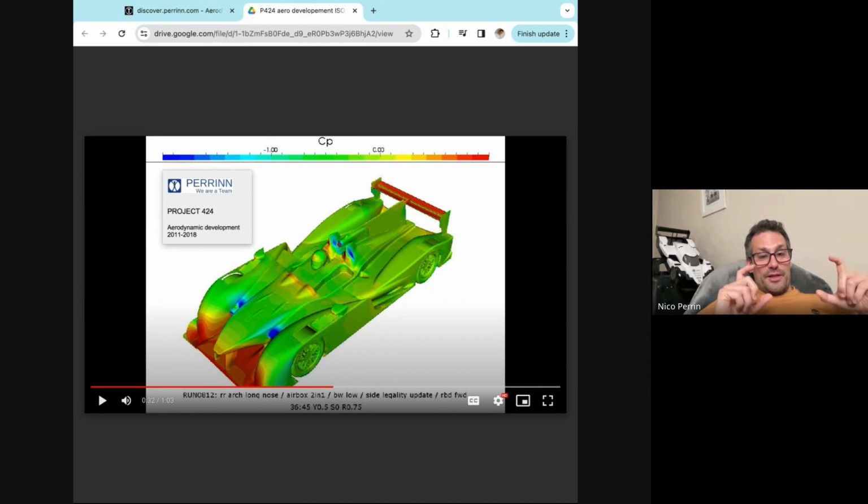So as an aerodynamicist, if you don't have the experience, you need to work with someone who will say, we need this much cooling. We need this much airflow coming in for the brakes, for front and rear, for the engine. So yeah, absolutely, these things are important.